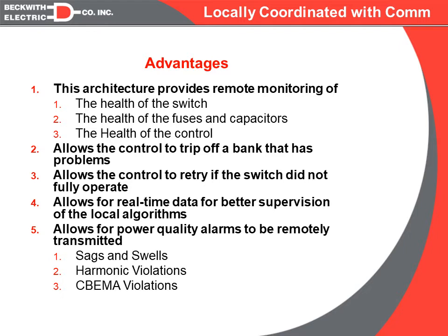And if the neutral current was not due to an operation, we can actually trip and lock out the bank so that we can reduce the amount of both neutral current and possible neutral voltage.